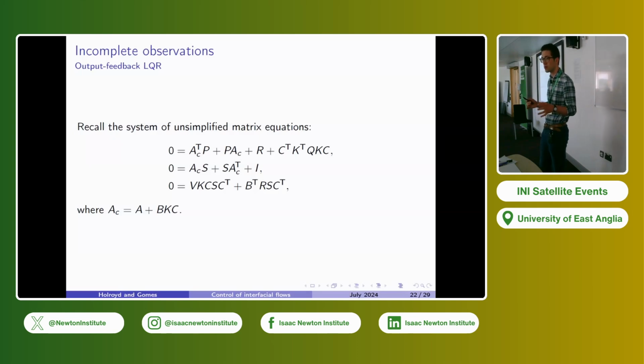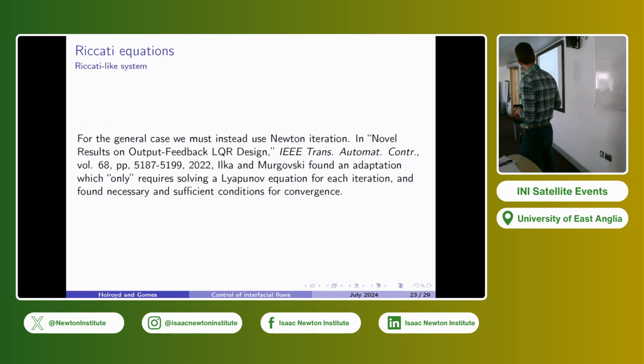And yesterday we talked about how we can do some clever numerics to solve the algebraic Riccati equation, and I'm not going to go into detail about clever numerics to solve this one, because there isn't a huge amount we can do. There was this paper quite recently, which tells you how difficult this problem is, because this is a really classical problem in control, and it's only very recently that we've got good converging algorithms for finding this thing. And so essentially we have to do an iterative procedure to find these matrices, which is sad because it takes forever, because solving the Lyapunov equation, the limiting step, is quite slow.